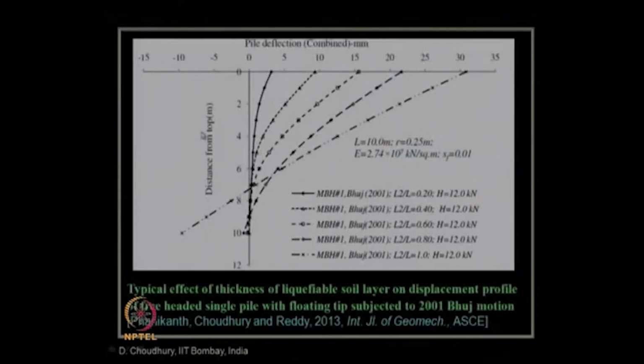Also, as the ratio of the liquefiable layer to the total length of the pile changes, increasing from 20% to 100%, you can see the pile deflection is also increasing like this.